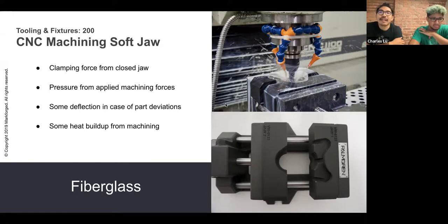Rather than saying, let me fill this part up with carbon fiber and just go for it, I like to use concentric rings of fiberglass. I've got one machine set up at home, essentially an Onyx Pro, a Mark II, but I only use Onyx and fiberglass on it because it's quick and low cost. It allows you to print at 100 microns still, and if that's not enough and you need it to be stiffer, you can always switch from fiberglass to carbon fiber. If this part is under heavy impact loads and is eventually breaking, you can use Kevlar because that's going to keep it from tearing.